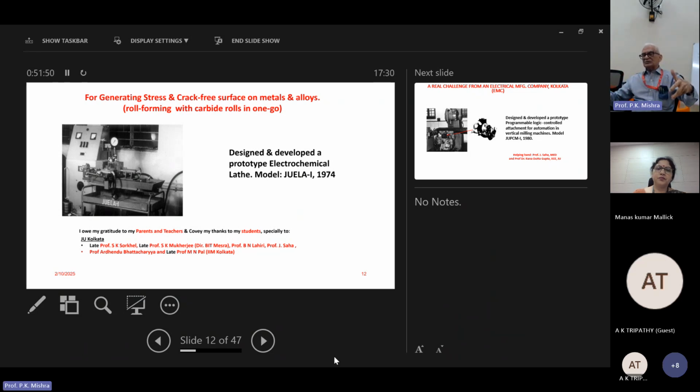We are using high carbon steels or tool steels as the rollers and then try to machine them. But we should give only one because you will not get the accuracy. If you have some process, you can directly machine the rolls, and the form will give the component in one go. So the machining is less, the machine components are reduced, and the surface is stress-free, crack-free, which is the requirement for rolling. We did this on a small scale because we can experiment with a form. This can be taken to any size depending on the job size.